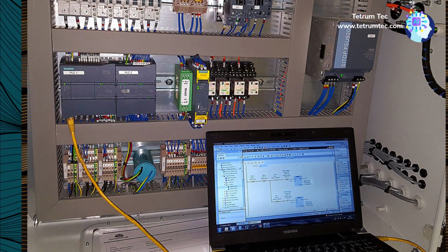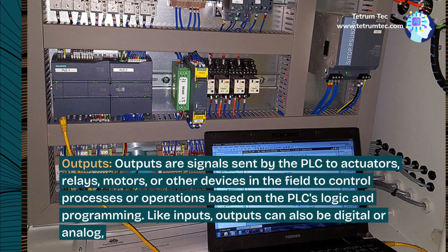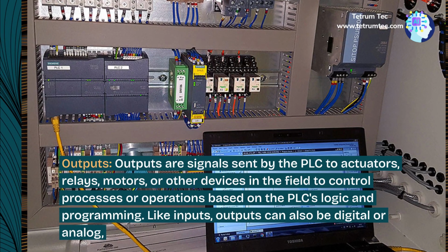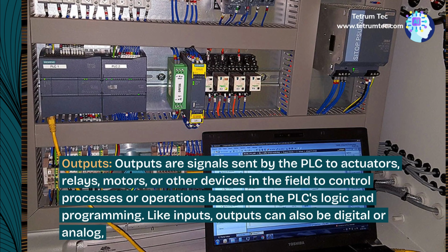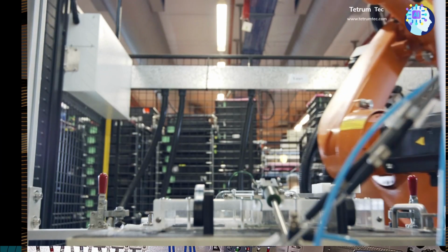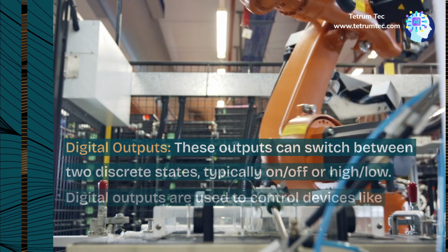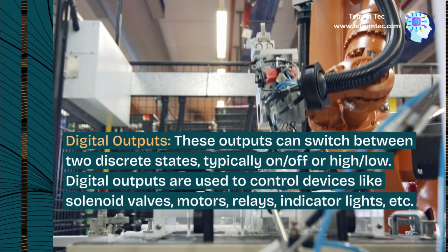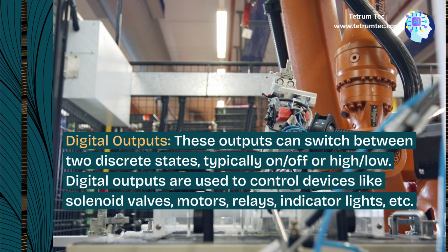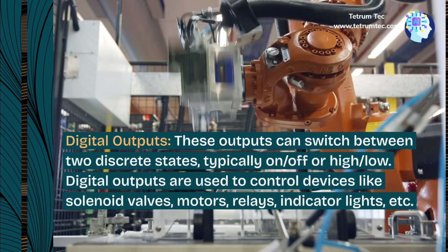Outputs. Outputs are signals sent by the PLC to actuators, relays, motors, or other devices in the field to control processes or operations based on the PLC's logic and programming. Like inputs, outputs can also be digital or analog. Digital outputs. These outputs can switch between two discrete states, typically on, off, or high, low. Digital outputs are used to control devices like solenoid valves, motors, relays, indicator lights, etc.